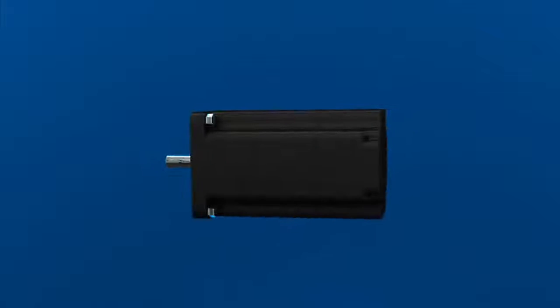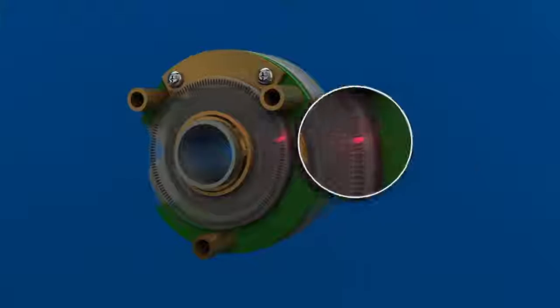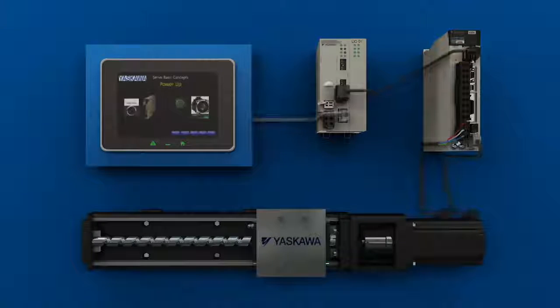A feedback device called an encoder is built into the servo motor at the back end. Now this is an example of an optical encoder. It's a disc mounted on the motor shaft. As the motor rotates, small photosensors detect lines on the disc. The electrical pulses from the photosensor are sent back to the amplifier. The amplifier uses the data to control the motor's position, speed, and torque.